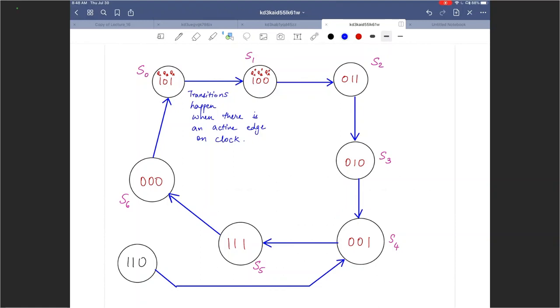All right, so while you guys are thinking of questions, let me also ask you this. Suppose as a designer, I say, if it randomly powers up at 6, I want it to go to 3. Is it possible for me to design that counter?